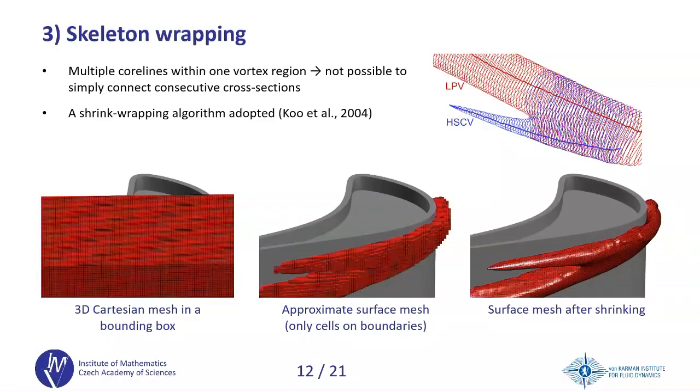If you do CFD, you may know this approach for the generation of meshes for faulty geometries. So if you have some CAD model with some missing faces, for example, or intersecting faces, some low-quality CAD model, you can use this shrink wrapping approach to create the surface that just wraps this geometry and then you generate your mesh.